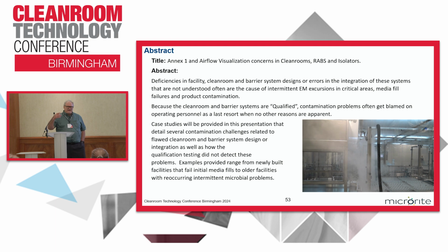I'm going to share some case histories today, and talk about airflow visualization, and how intermittent problems were related to some facility design issues or operational issues. The video here is from a facility. On the left here is a fan-powered HEPA cart, or a cart or trolley used to transfer components, partially stoppered vials, which would be loaded here on the right. And during the smoke studies, we had this issue at the interface.